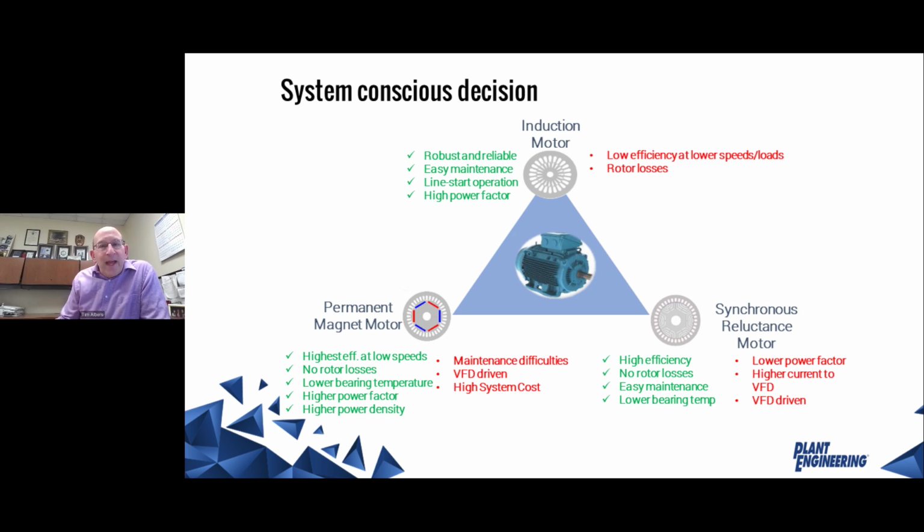Permanent magnets have some high efficiencies. But you know what? You have to have a drive, and there's a little bit higher system cost, and you can have some maintenance issues, and it's going to be a little more complex to set up. Very similar to some of the synchronous reluctance. The other thing is the synchronous reluctance also has a lower power factor. A little less complex because there are no magnets in it. So there are always trade-offs between efficiency, maintenance, cost, robustness. So what I'm going to tell you is there's not a single technology that is a solution for everything, but there are going to be some advantages and disadvantages to each.